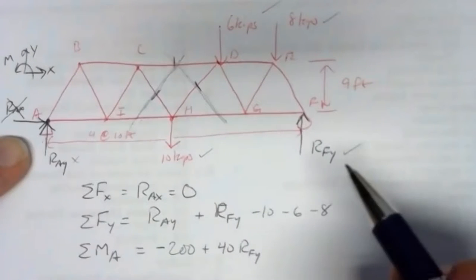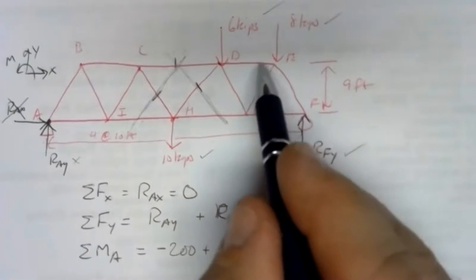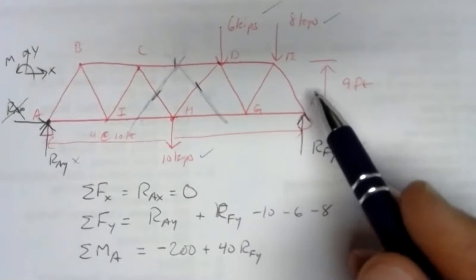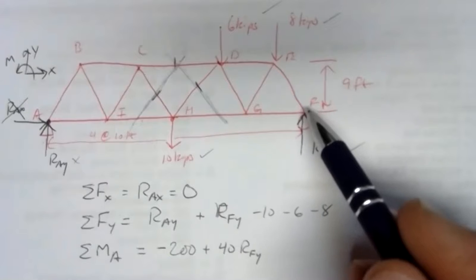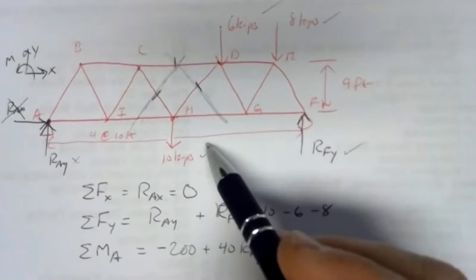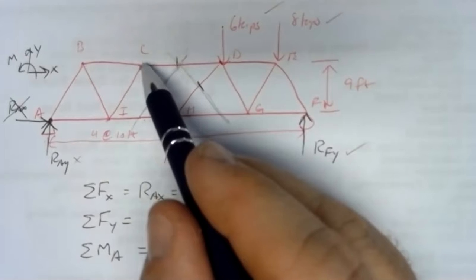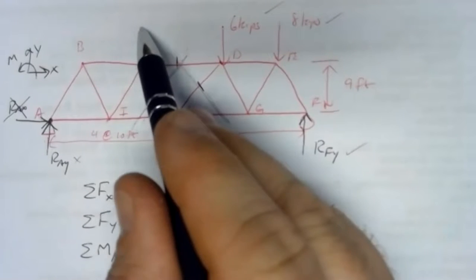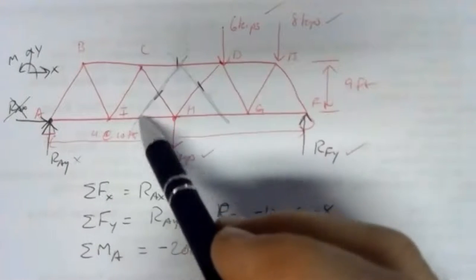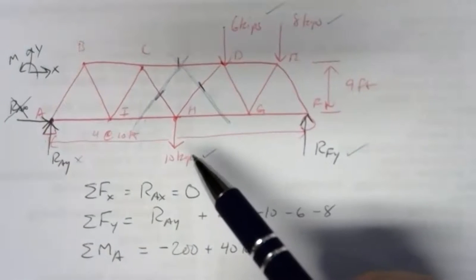The 6 kip force and the 8 kip force, we'd have to do a little bit of assuming here that this is a relatively symmetric structure. We really don't have anything in the problem that explicitly tells us that. This could be offset just a little bit to one side or another, so we wouldn't necessarily be able to see it, but we're down to whether we either make the assumption that each one of these triangles is essentially equilateral, so that we have a straight line coming down through here, not equilateral, but at least it's isosceles, that we've got a straight line coming down through here that would give us equal sides. We can't do the problem if we don't assume that.